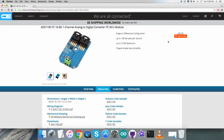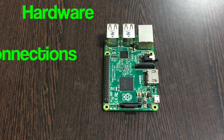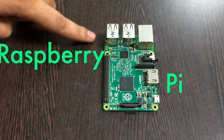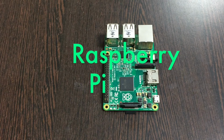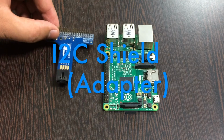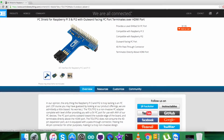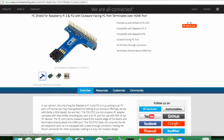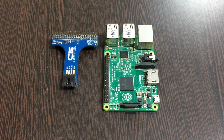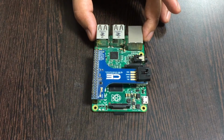Well, what we require next is to have a look over the hardware setup, the connections we need. Let's have it. Well, in the hardware setup for the connections, what we require is this Raspberry Pi, which you are able to see on my screen, and these are the GPIO pins of the Raspberry Pi. Next, we require an I2C Shield, which you can see, and it's available on the website controleverything.com. The real reason we are using this shield is to make easier connections with other I2C devices. So for that, gently place the I2C Shield over the GPIO pins of the Raspberry Pi and make a connection.